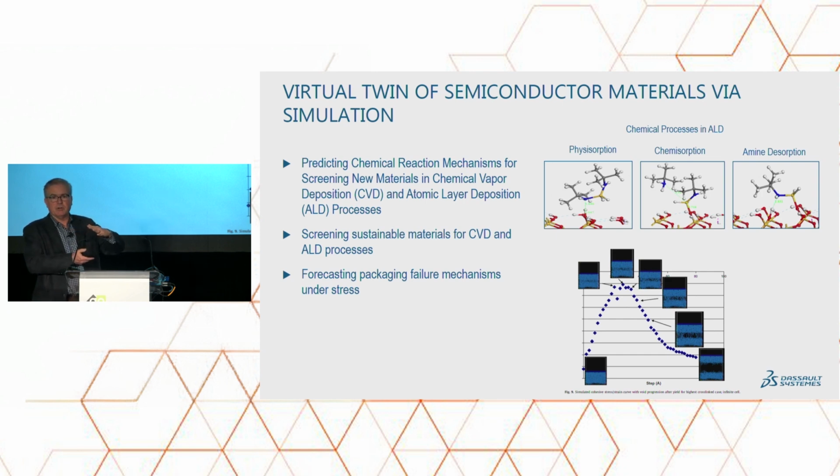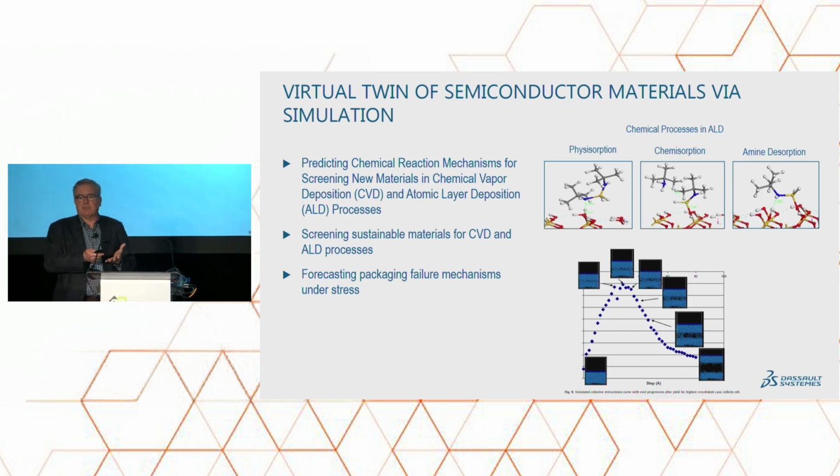we have the packaging material, a cross-linked polymer mixture on top of the wafer layer, and then we're applying a stress strain simulation, so gradually delaminating it, pulling that layer off, and following the changes in stress to determine, okay, what is the deformation mechanism? Is it a simple delamination? Does the packaging material itself begin to fail on its own before delaminating? So this is used as a way of being able to screen different materials to be able to determine, okay, how will different polymers or other types of materials form this surface to help in the packaging and protect that.